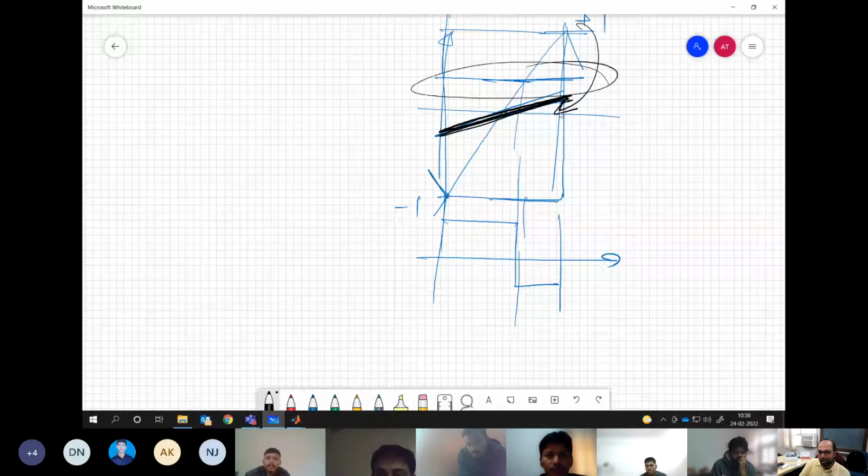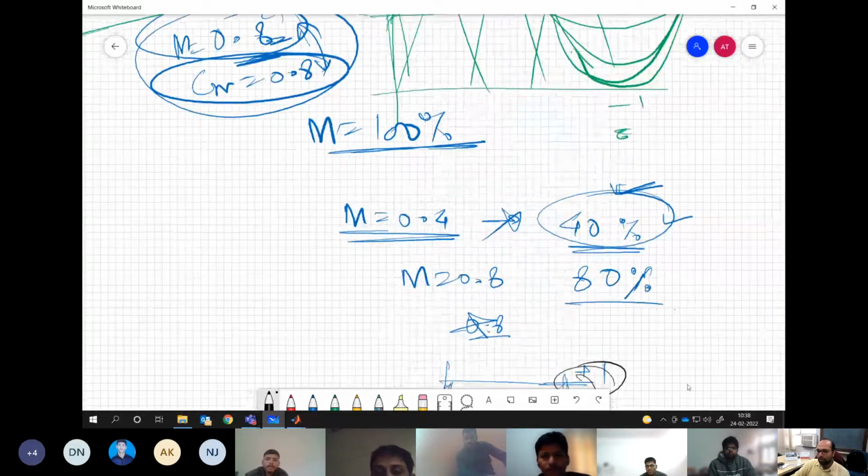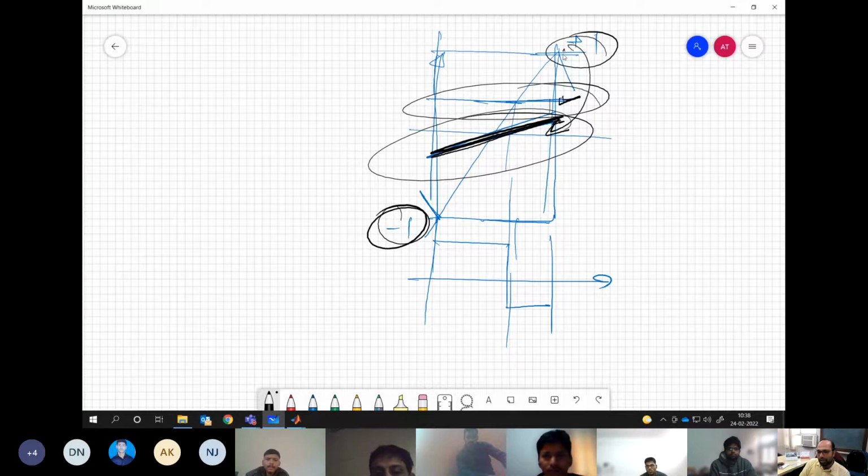What is the meaning of modulating signal and carrier in this case? If this is not intersecting at all, what is it doing there? Why is there a carrier? Why are you changing these values? I am still surprised, shocked actually. Who asked you to change? Of course, if you change, because your relative value is changing, the relative value between the modulating signal and the carrier is changing, so of course you will get a wider pulse. What is the problem in that?